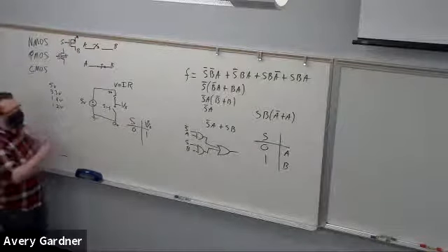Okay, but what we want to do is we're going to lose 5 volts over that. When this closes, current flows, it drops. We end up with zero on the output because it's closed, it pulls it to ground, right? It looks like this. If you draw it out explicitly, it's pretty obvious that this node Vx is directly tied to 0 volts and is therefore 0, off. Don't be afraid of redrawing circuits like this in order to make it clear to you what's happening.